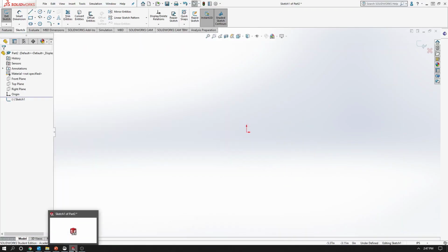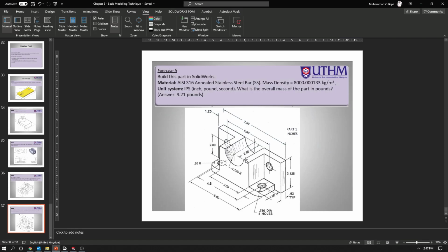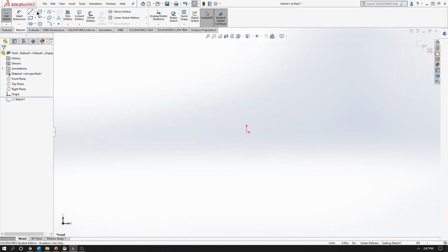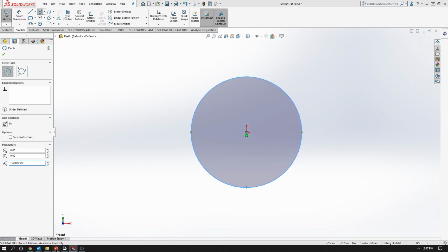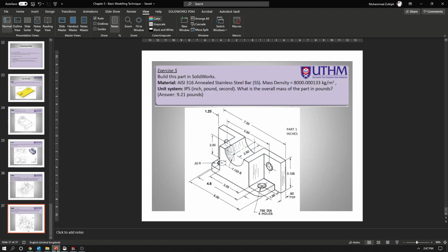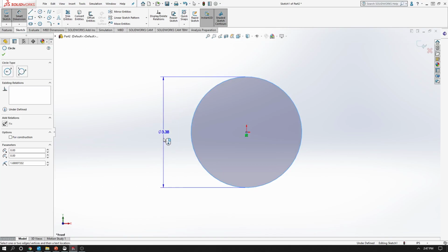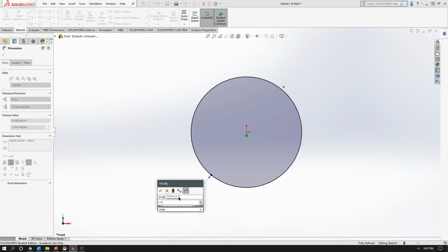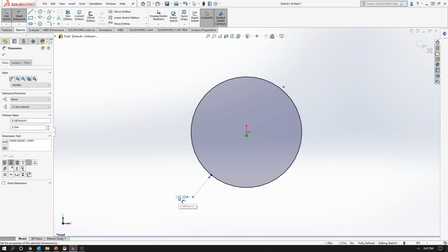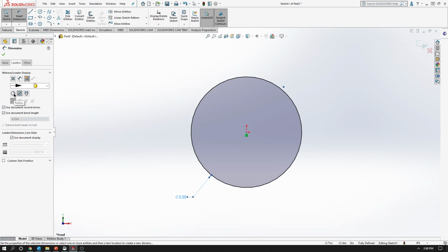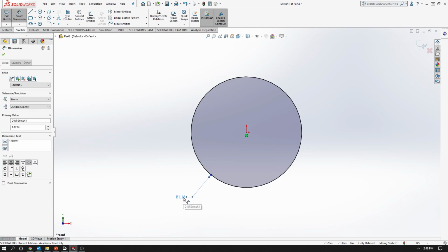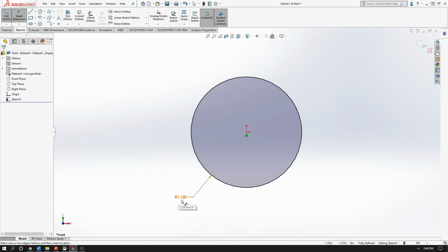So first, if we take a look according to this drawing, they have a hemicircle here. So we draw this first. So we go to the circle, and then always make the drawing at the origin, and then we take a look at the dimension. The dimension would be 1.125 radius. Alright, so we click here, 1.125, multiplied by 2 because the dimension is in diameter, and if you want to change it into the radius, we can go to the leaders and then click add radius. So if we have two decimal positions, we can change the tolerance into 3. Okay, so the radius will be 1.125.